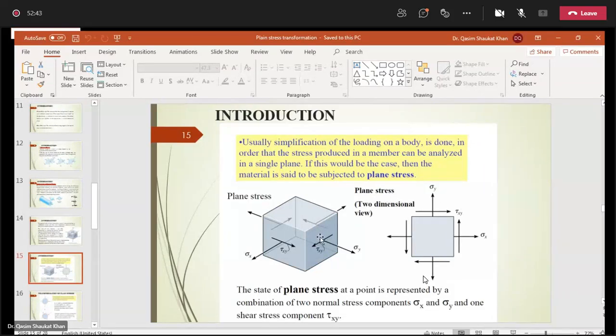This one is the complementary stress, which is in the opposite sense. So if I can find this shear stress, I can know the values and signs of all these four shear stresses. Similarly, if I know the value of this sigma x, I can know the magnitude of this.